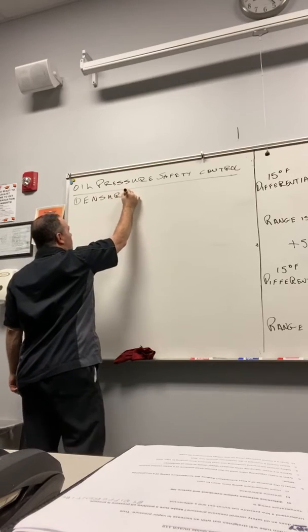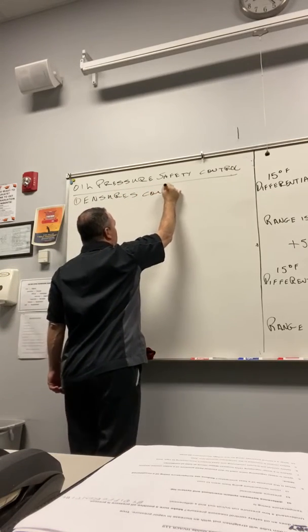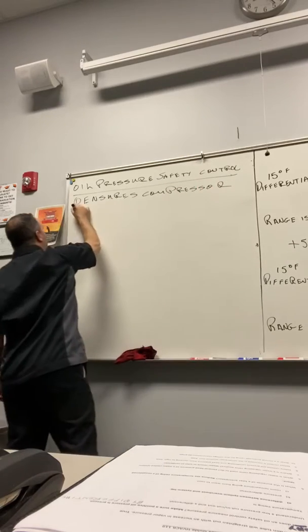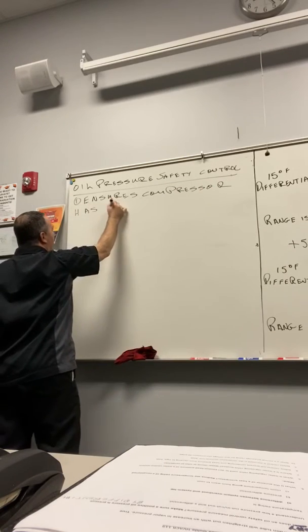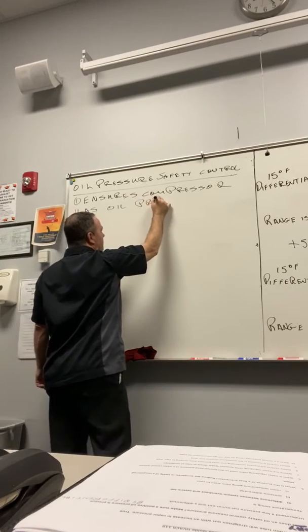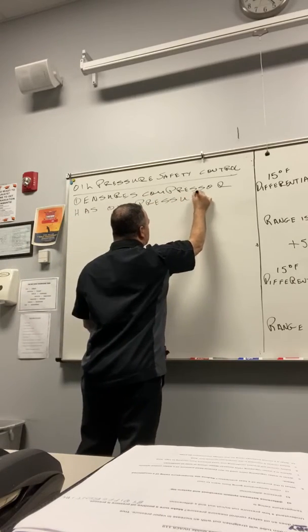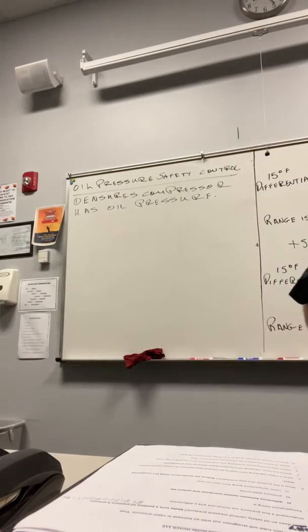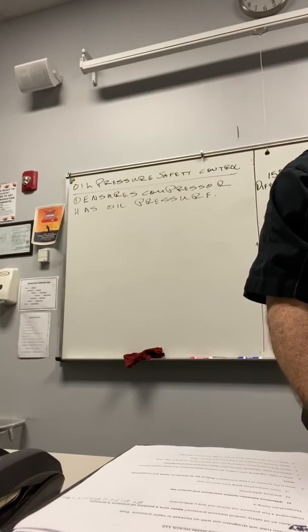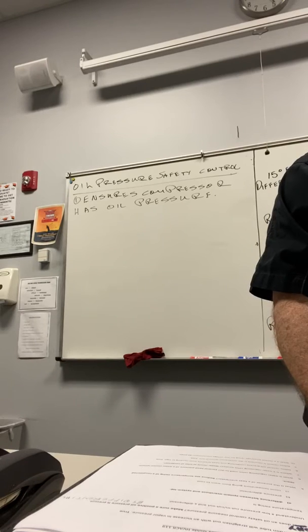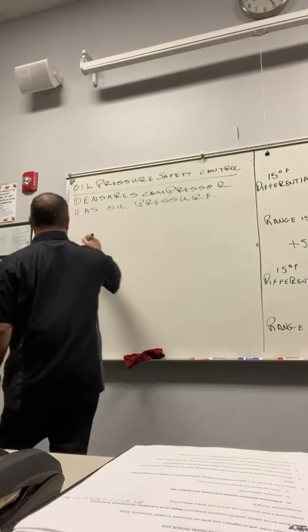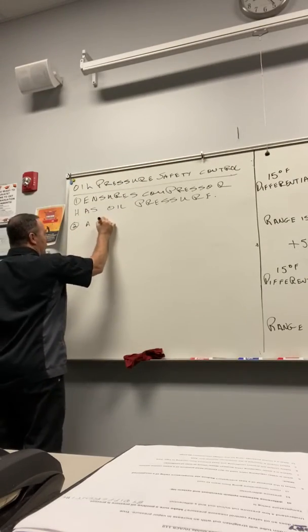It ensures compressor has oil pressure. That's what this is doing. So, if it's not sufficient, the control will open its contacts and turn the compressor off. The control is a pressure differential control again. Once again, it's a pressure differential control.